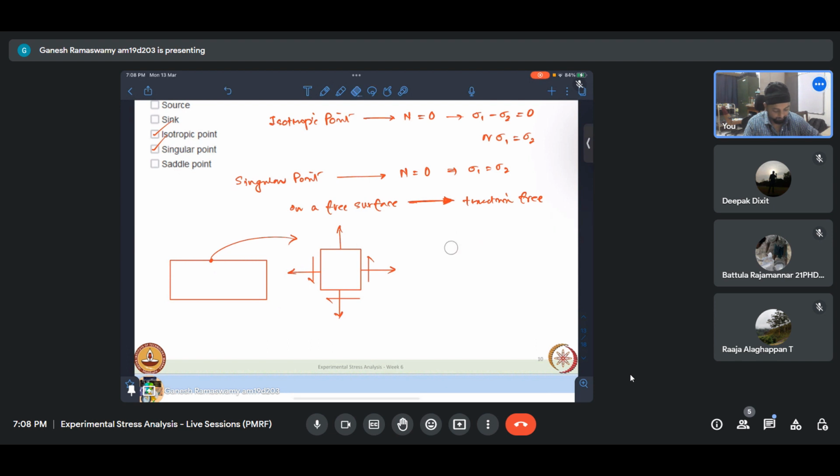Shear cannot exist because shear cannot cross a free boundary, in which case all my cross shears do not exist. So I'll delete all of them. And since this is a free surface, my normal stress cannot exist either. So essentially it's a traction free surface. Traction can have two components, one normal and one tangential. Both are zero.